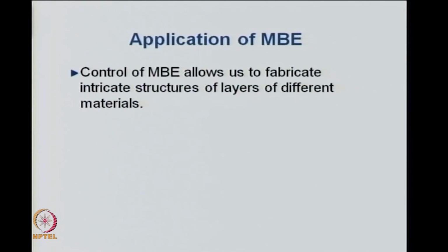Finally, the application of MBE: the control of the molecular beam epitaxy method allows us to fabricate very intricate structures of layers. So, you can precisely make, say, a 10 layer system or a 4 layer system, with each layer having the conditions that you want by properly choosing your flux, that means the molecular beams, and the temperatures, etc., and the substrate.